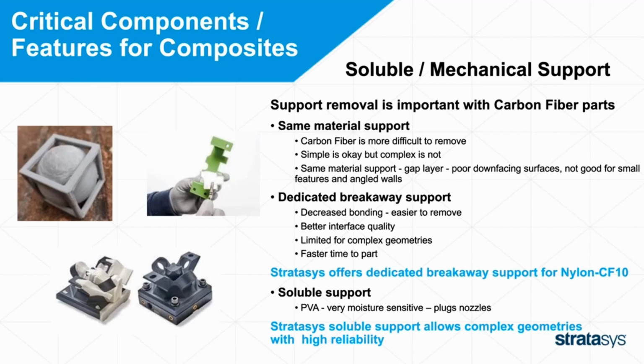And so you get very good part quality. It takes that time to remove that soluble, which typically, with removing the part, putting it in a tank of liquid, and then drying that, takes about half a day to a day longer. But you can get, like you see on the left side, a very complex part. You can have support removed without wrecking the part and still have very good surface quality.